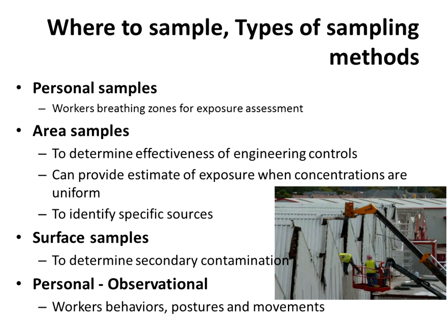Where to sample, and this is also, I guess, how to sample and the different types of sampling strategies that you can use. So the most popular, I believe, is personal sampling, and that's when we're trying to represent the air in the breathing zone over the sample medium with the pump, what the worker's dose is, or what their exposure is. Their exposure, when it's gotten onto the sample media, is a surrogate for their true dose, but this is what we're using to evaluate or assess their risk in the workplace.